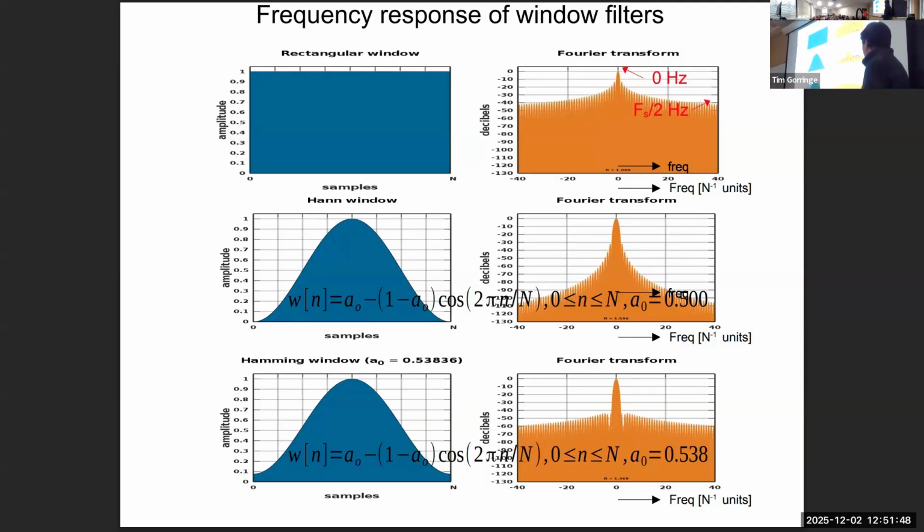Another feature that you see in these plots, you can probably make it out, is this little high frequency structure in these plots. And it's in all of these plots to greater or lesser degrees. Think about the ordinary weighted average in the rolling filter. If you have a period of a signal that exactly matches your window over which you're calculating the average, so if the period matches the window size, then that signal can't get through that filter.